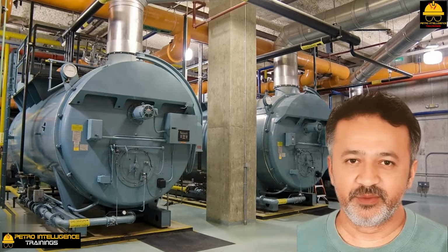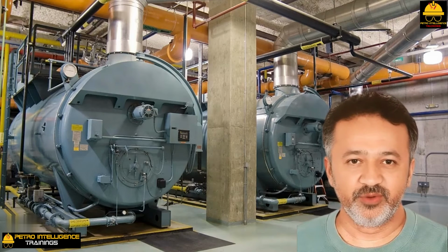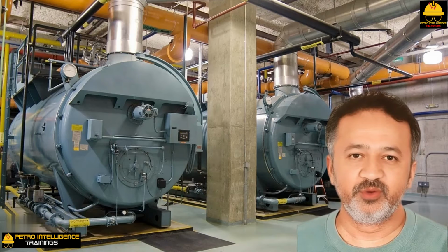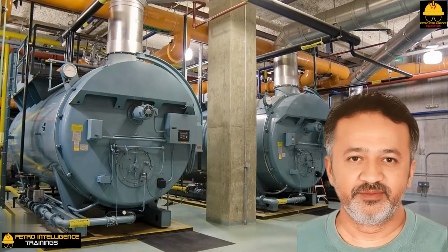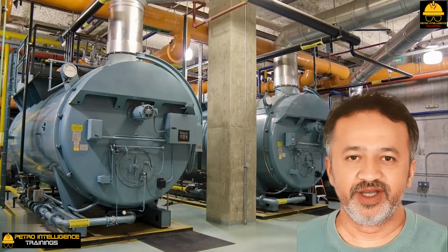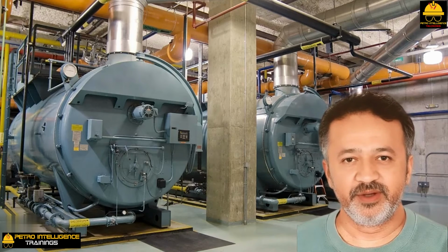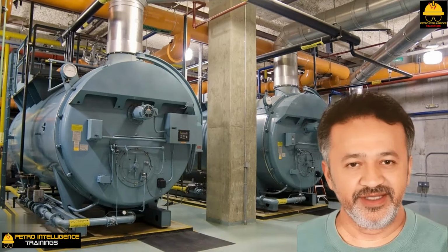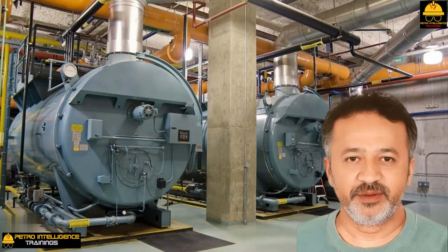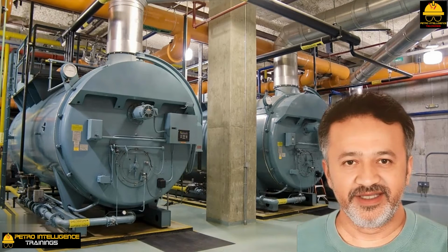The supplier had supplied the retrofit design for their crude unit distillation tower fractionation trays. The startup went well, and his new tray design worked fine for 2 days. Then the furnace steam superheat coil failed, and the unit was shut down. During the second startup, the operators inadvertently filled the tower to the top with crude oil and damaged all the trays. The tower would no longer fractionate.